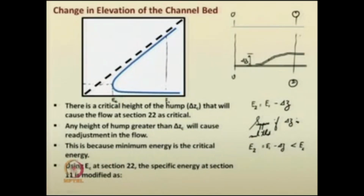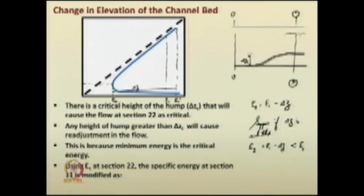From that you need to take into account del z in such a way that the specific energy at the upstream section gets modified. So, the critical depth will be followed here, then it will change the upstream conditions. So, you will see the corresponding depth y1 dash, this was the actual depth y1.